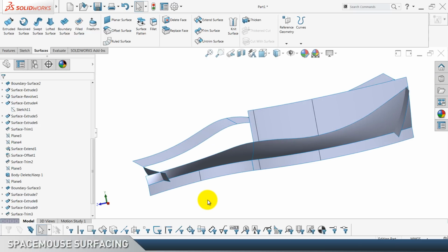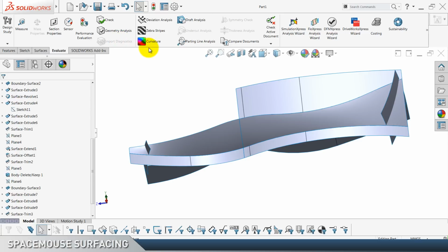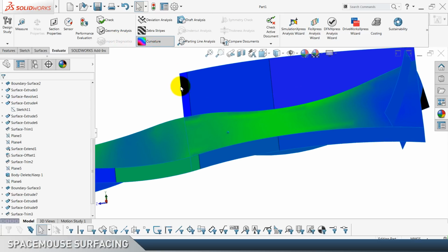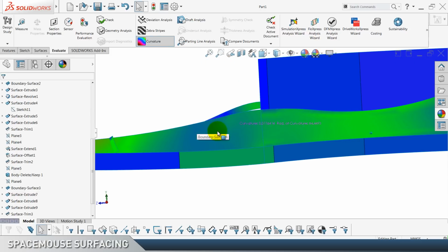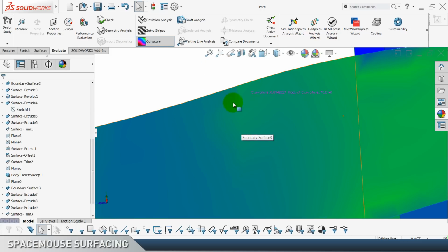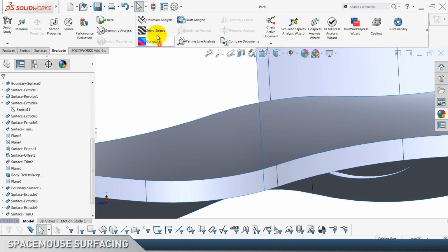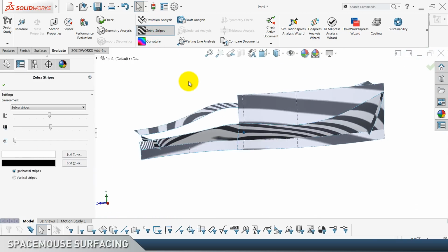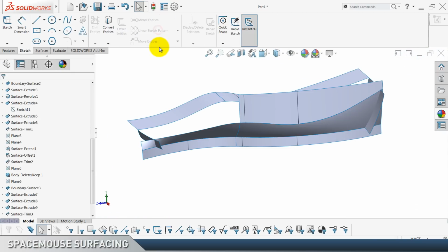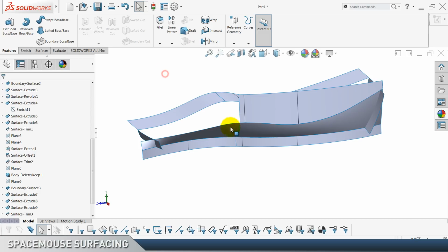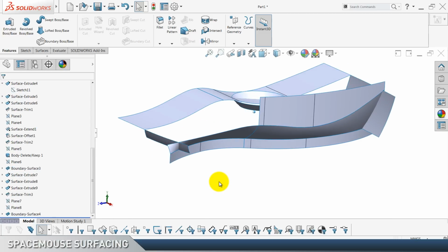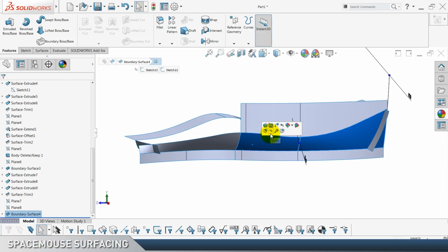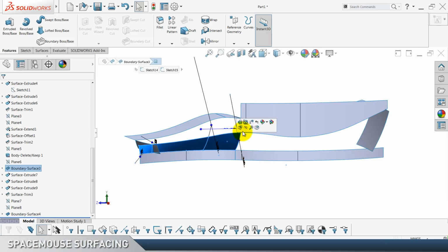Now let's just check something out. If we turn on the curvature, you can see that this last surface we built is not really perfect, neither this one is. You can see here small snapping, but we actually have all these inputs we use to create these two surfaces to now create third, and let's hide this one.